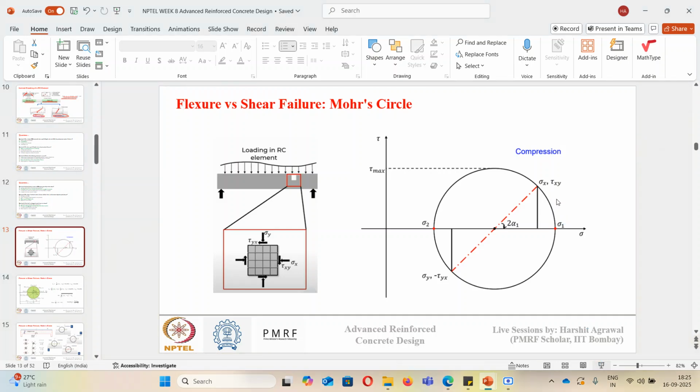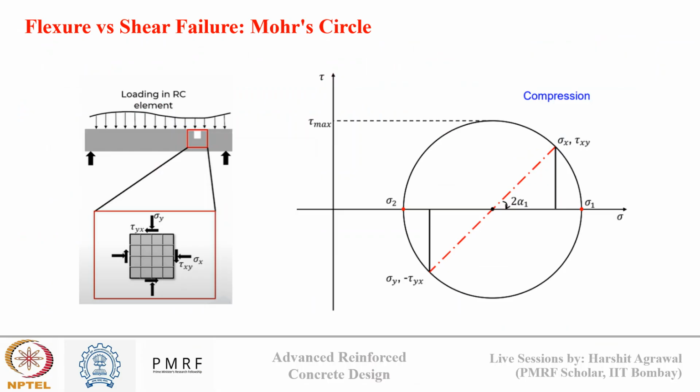Okay, now we'll move ahead to talk about Mohr circle. In one question, if you remember in the last slide, a term was used: principal stress, which, going back to the earlier discussion, means the maximum and the minimum stress resulting from the combination of two stresses. Principal stress can be the maximum stress and also the minimum stress, which results from the combination of multiple stresses acting at a location. To calculate principal stress at a particular location, we use Mohr circle.